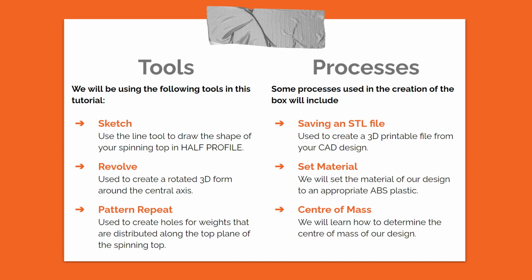So things in additive manufacturing tend to print a bit smaller than our original intention. So if you make a hole of 5 millimeters diameter, it tends to print out at about 4.6 millimeters diameter. So you lose a bit of that precision there. It can be reliably inaccurate, so you can actually change your model in easy ways to account for that kind of thing.